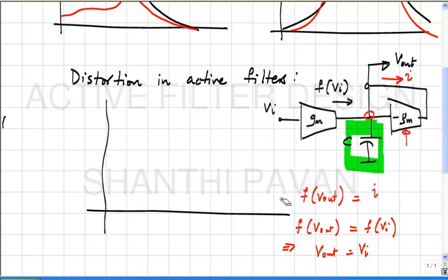So what makes sense is to put the input tone somewhere in the middle. Now the question is, where is the middle? There seems to be a lot of middle. Okay, like as I go on, pardon? Yeah, so within quotes, a good place to put the input tone is to make sure that the input frequency is high, but if I go on making it too high, the harmonics start going out of the band. So what is the logical place to put the input tone, such that the third harmonic, which is the dominant harmonic, lies at the band edge, right?